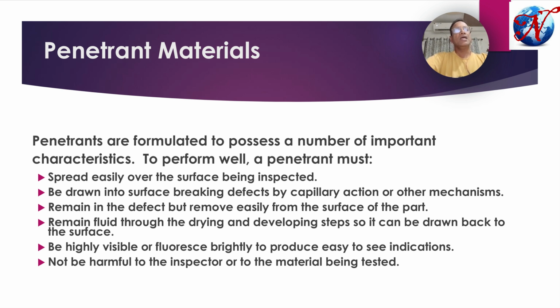Definitely, the liquid that will be used as a penetrant shall be chemically inert. That means any kind of toxicity and flammability will be under control, such that when we use that liquid penetrant during inspection, it will not be harmful to the inspector.